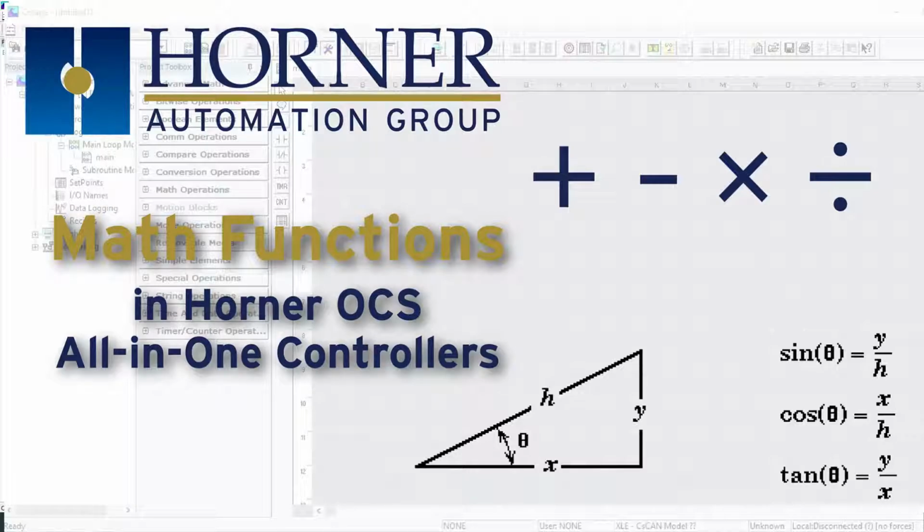And then whenever you are doing math that involves a mix of different variable types, from integer to floating point or whatever the case may be, there are also what we call conversion operations, for converting from one type of variable to another. So we're going to cover all of that. Again, we're starting out with advanced ladder register based, but we're going to go through the other languages as well. And as a teaser, I'm also going to show you a couple of ways of actually using logarithmic and trigonometric functions in real world type applications. So you probably thought that wasn't even possible, right? Okay, let's go ahead and get started.